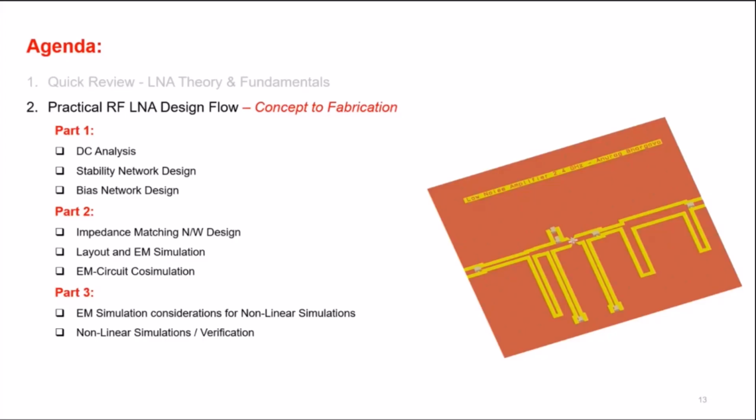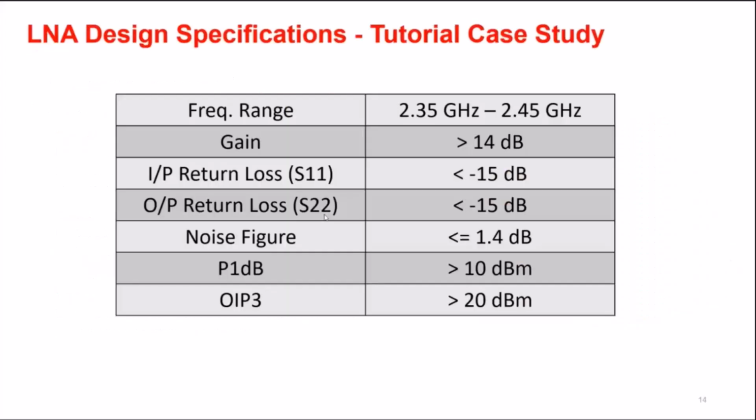Can we get manufacturing related files for RF PCB using ADS, similar to software like Altium? Yes, absolutely. ADS has a fully featured layout tool. It can generate Gerber files, DXF files, ODB++ files, any file which your fabricator needs. Once you use ADS for this kind of RF board, you don't need any other PCB design tool. Everything can be done in ADS, and we recommend you do everything in ADS, as you will see the reason once we go to EM circuit co-simulation.